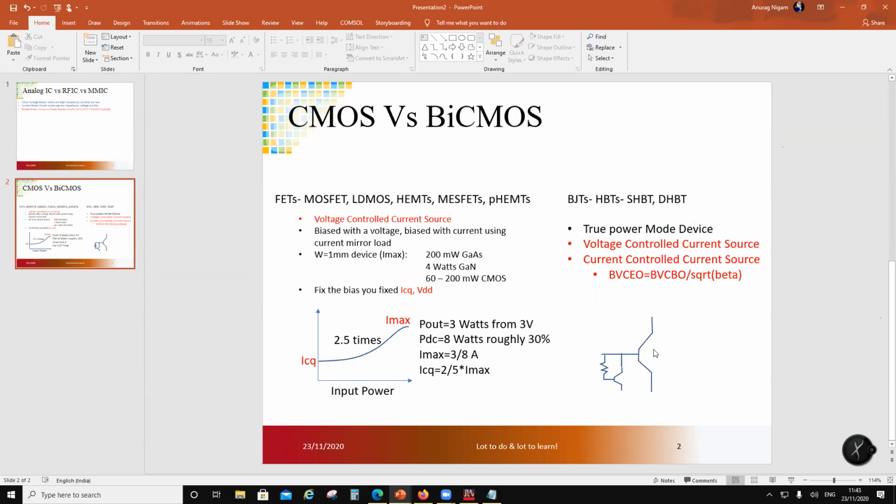The SiGe transistors can go up to 12 volts, while silicon transistors break down at around 3 or 4 volts. So IBM has a process which is like 4 volts, 5 volts, or for PA, they have a process which can go up to 10 volts or 12 volts. This is because they are doing some kind of semiconductor physics in the channel and the collector base junction for the breakdown. So you need to know the process to be a circuit designer. So I cannot